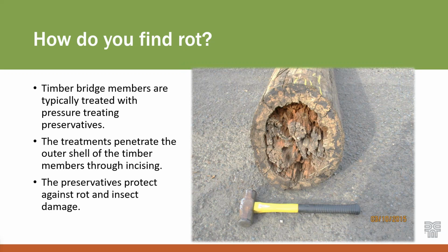And so typically these piles rot from the inside out. This is a particularly not-great pile that was removed from service, over here on the right in the photo, and you can see that the material on the inside is completely rotted out, and you are left with basically just a shell of timber around the outside, which makes inspection and finding these particularly challenging.